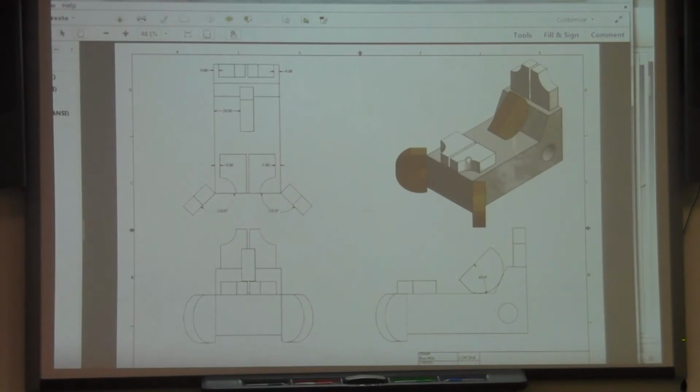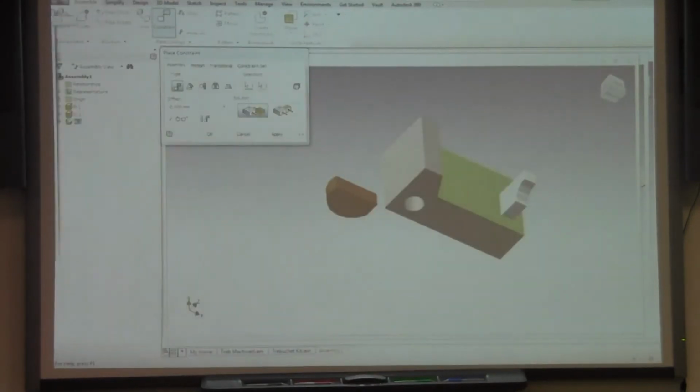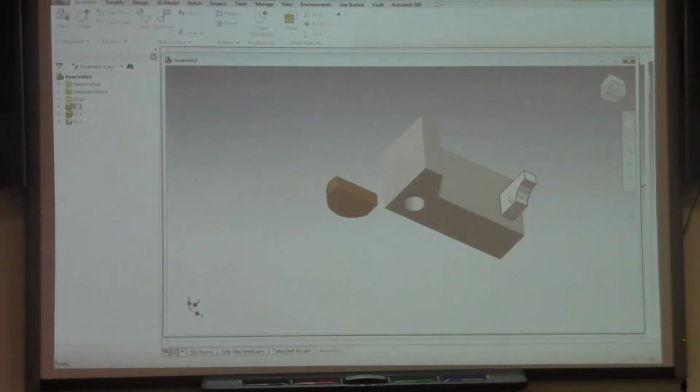This is what we're going to make, which means that I've got to delete that constraint that I just put in place. Easy enough to do. And then I lay them both flat, and I give them this dimension of 4 units right there. I'm going to slide this out of the way. I'm going to apply this constraint simply so I can delete it, so I can show you how that's done. I'm going to apply the constraint. I'm going to kill the constraint dialog.